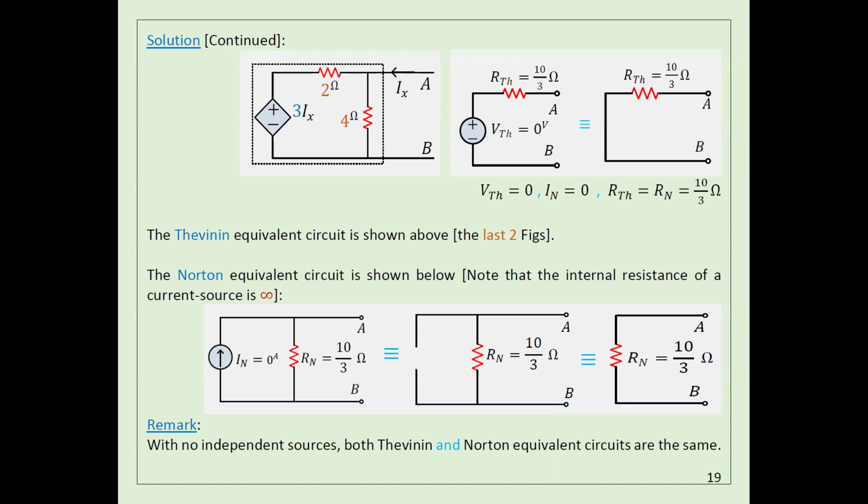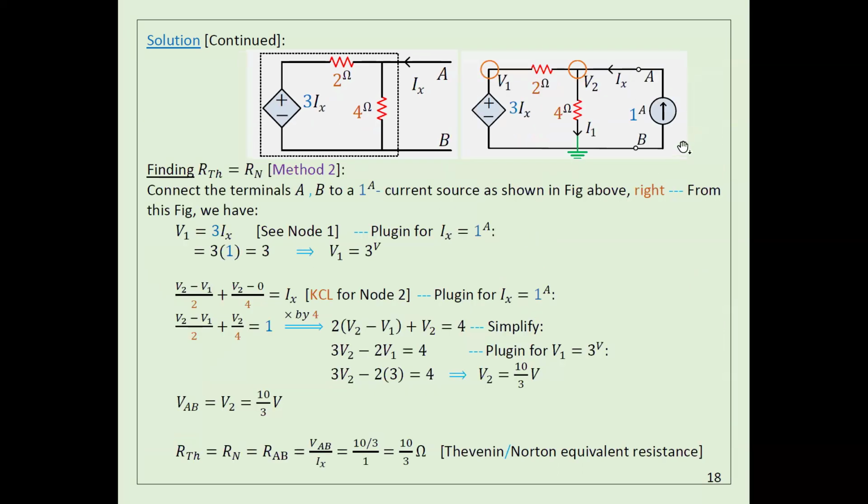Yes. When there is no independent source, the energy is going to come from an independent source. For dependent sources, the amount of voltage or current depends on the voltage or current of some other elements. If there are no independent sources, that means there is no current, and voltage will not come from anywhere, because this is a mesh. Anyway, I told you there is another approach.